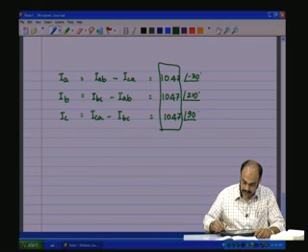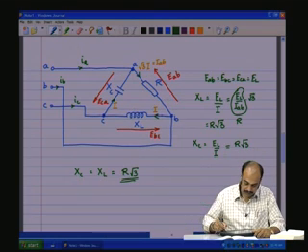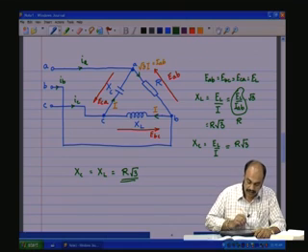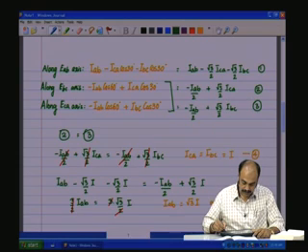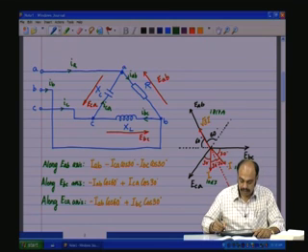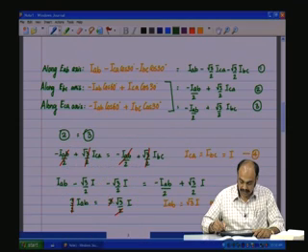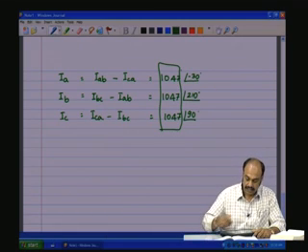However, you will see that in the case of the phase currents, we have this artificially included I and root 3 I, but effectively they all will cancel out if you put it along the 3 axes as we show using these equations, which effectively cancels out on all the other axes, and you will have just only the IAB component which will flow through that, which is the effective power. But from the line side, from the source side, it will look as though they are balanced.